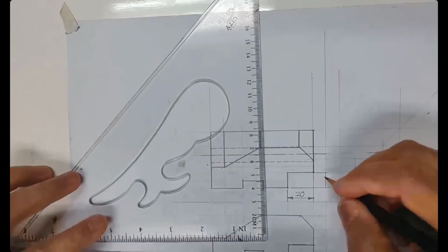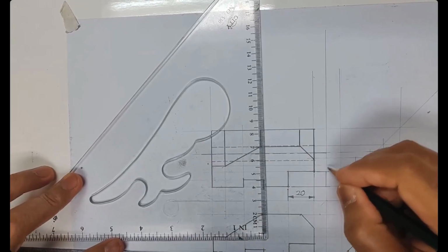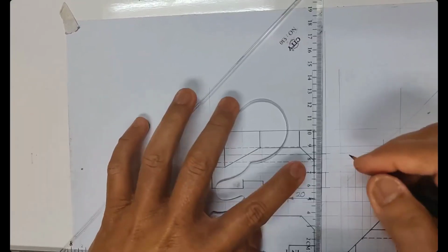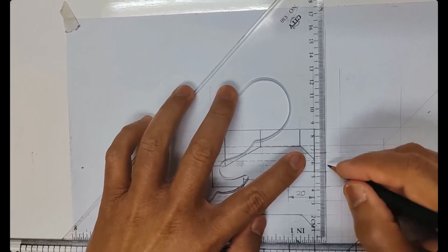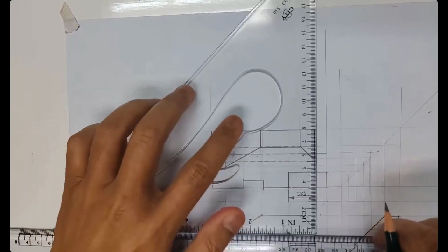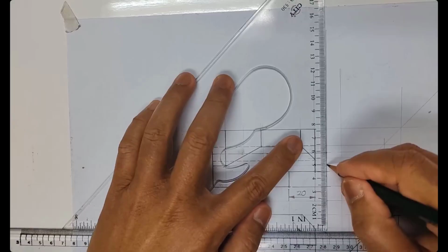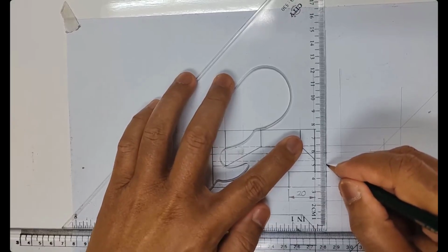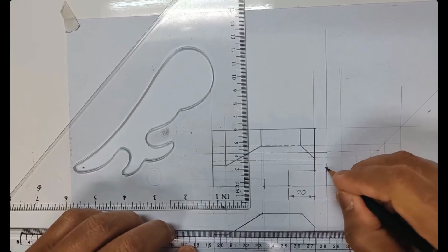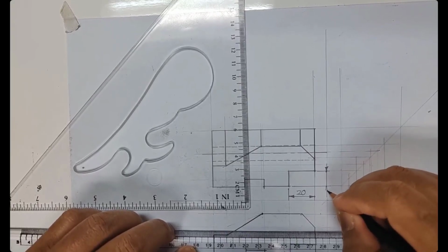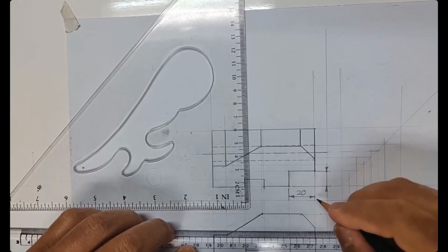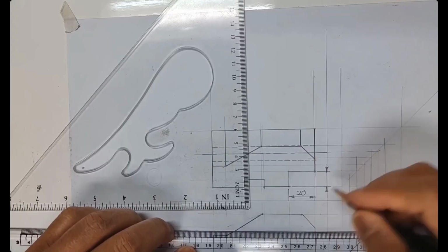If the gap is too small, your arrowhead cannot point outward, you can make it point inward. Okay, you can do that. For example, like this, the distance of this measurement or the unit is too small. You can do your extension dimension line like this, and the arrowhead is pointing inward, right? Inward. So this arrowhead is 3 to 1 guidance for how I do it. Alright, so we have a little bit of extension, 1 millimeter guidance. So can you see after the dimension I have 1 millimeter of extension.